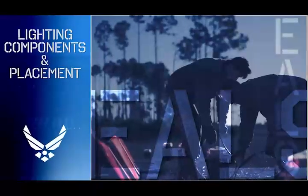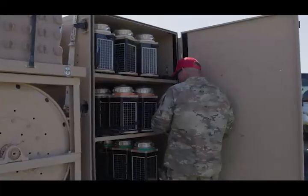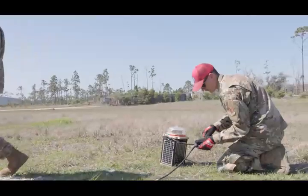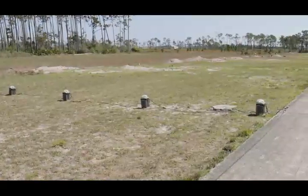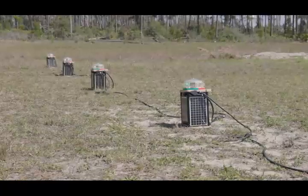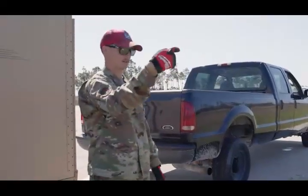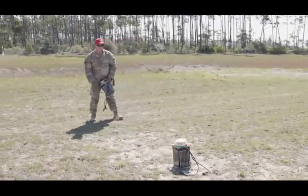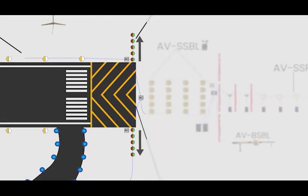Lighting components and placement. Let's talk about the lighting components and their placement. Threshold and end lights are spaced 10 feet apart from the wings of the runway threshold using 10-foot cables with green lights facing the approach. Place them in 2 groups of 5, with the innermost lights in line with the runway lights, for a total of 10 lights in a winged-out configuration.